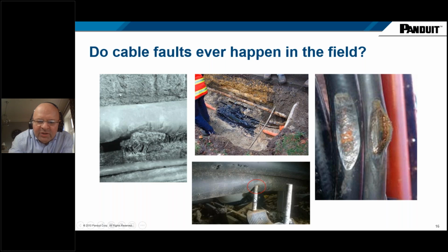And this was potentially the most hazardous, which is some maintenance work has occurred, and what's happened is the maintenance guy has lifted these cables out of this saddle and rested them on the threaded rod that you see here. Those cables were forgotten about and never returned to the cable cleat that was holding them, and the effect of that was it caused a short circuit some 15 meters further down the track and led to a potential hazard, but thankfully with no fatalities.